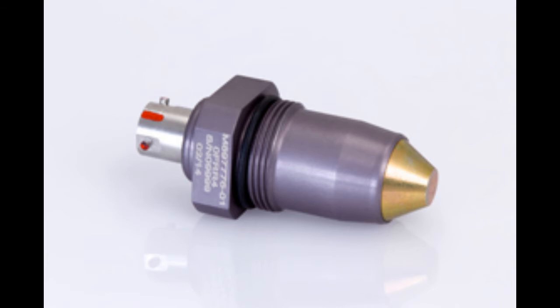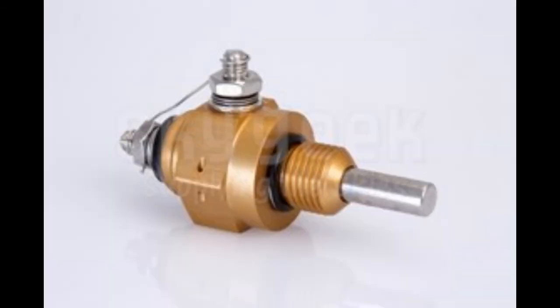The big thing about these squibs that I want to get across is that you need to be very careful when disconnecting the electrical connections. If a static charge or a voltage is applied to the terminals on the squib, you can accidentally discharge the squib. I've seen it happen before. So before we remove these cartridges, we're going to make sure that the cartridge terminals have been properly grounded, shorted, or shielded to prevent accidental firing.